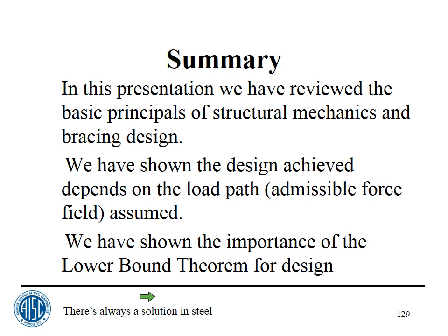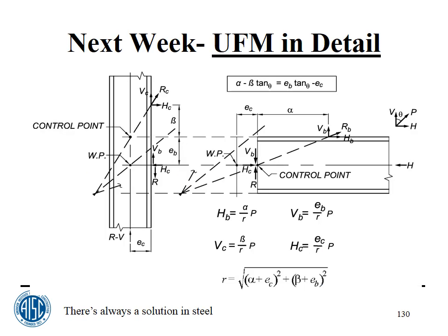We have shown the design achieved depends upon the load path. Your computer programs assume a load path. We have shown the importance of the lower bound theorem. The lower bound theorem converges to the true solution from the bottom. The upper bound theorem, which you're more familiar with, the yield line analysis, for example, converges from the top.